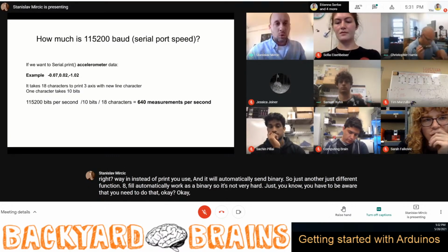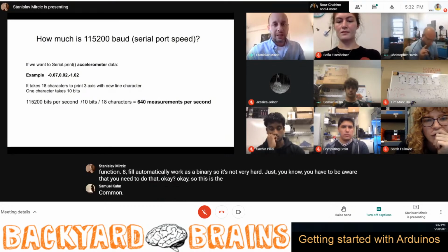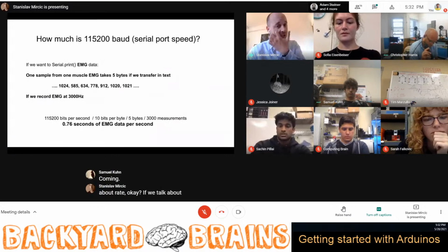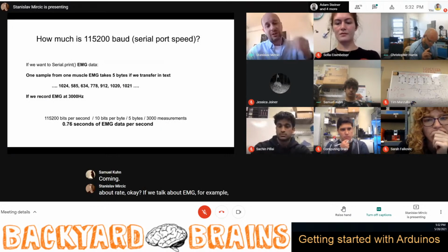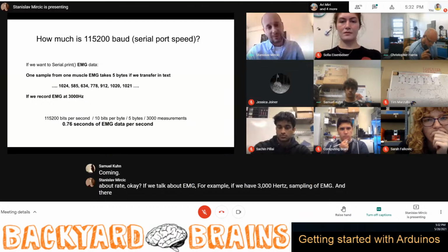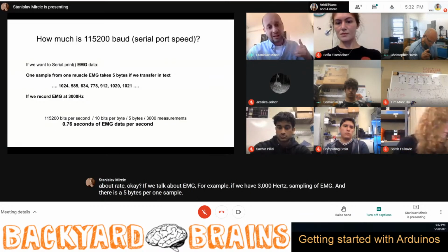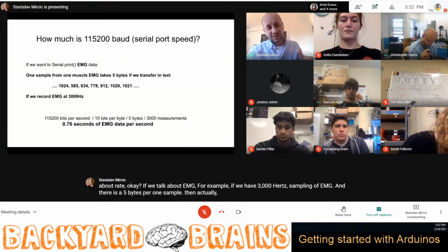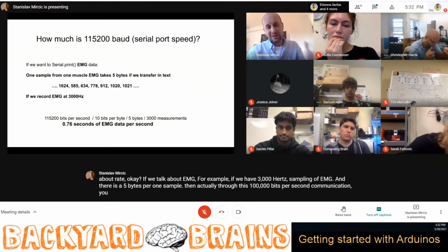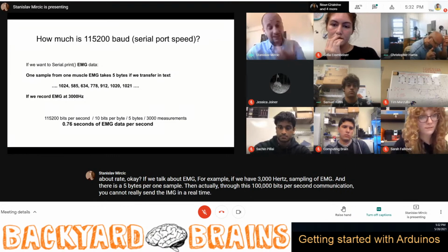Okay, so this is the communication baud rate. If we talk about EMG, for example, if we have 3000 hertz sampling of EMG and there are 5 bytes per sample, then through this 100,000 bits per second communication, you cannot really send the EMG in real time if you send it as text.